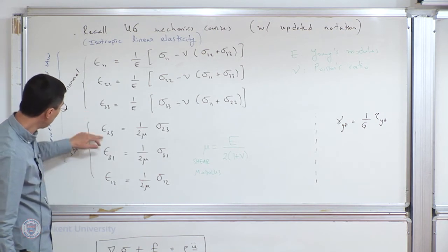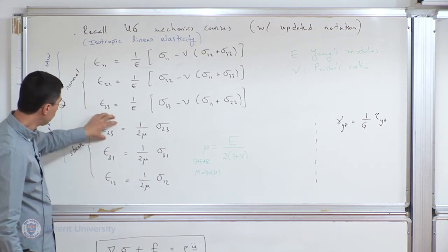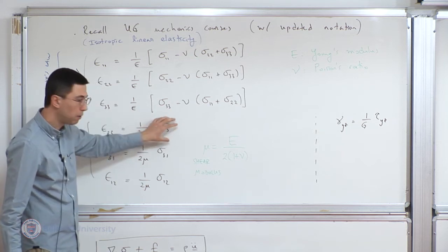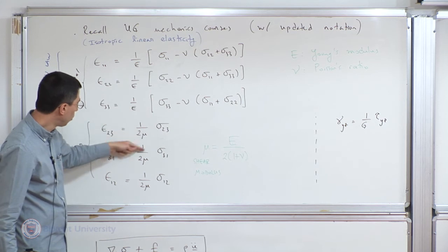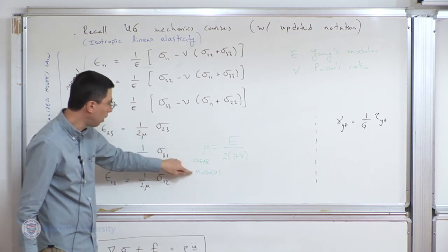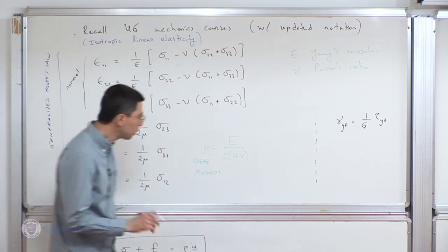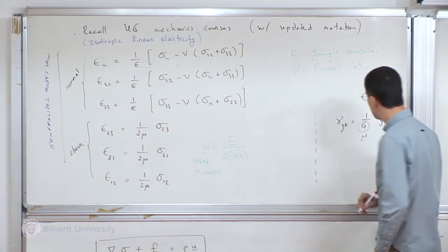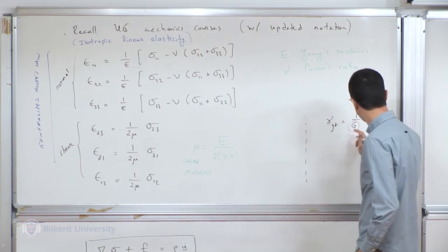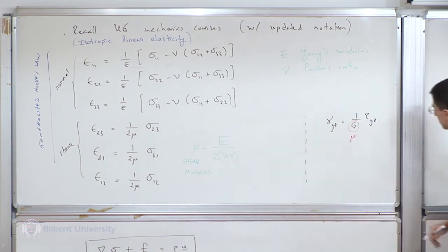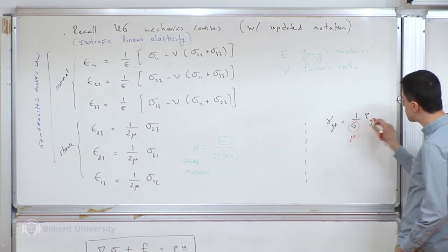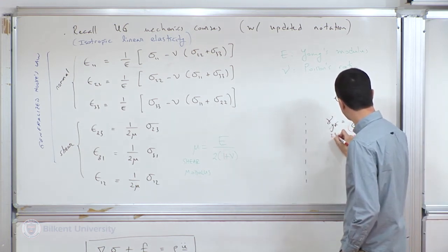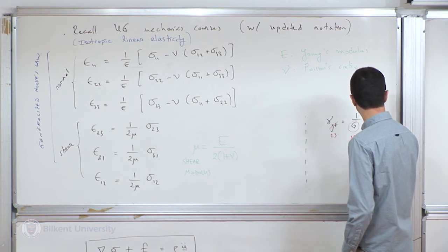And then for the shear components, this is what we have. For shear components, they are always related to only their corresponding stress or strain. And 1 over 2 mu. Mu will be our shear modulus. Slight change of notation. That mu we used to call G before. So mu is a more common notation. And so this is the equation that we used to write in 231. Now instead of YZ, I'm writing 2,3, right?